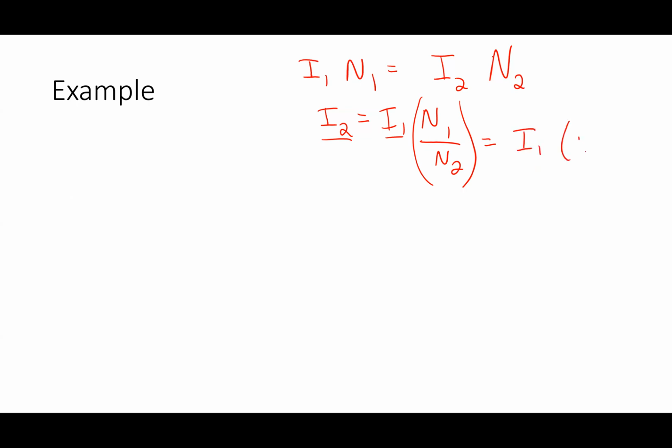In my brain, I think of it this way: the low voltage side has the higher current. It has to. So I don't even really think about N2, N1. What I think of is that there better be 10 times as much current on the secondary as there is on the primary. That's what I look for when I'm checking myself to see if I'm correct.